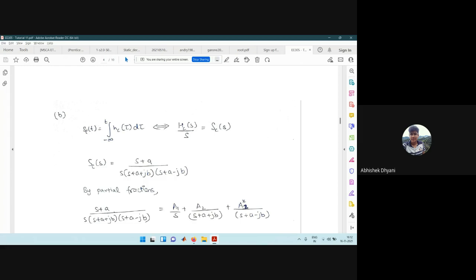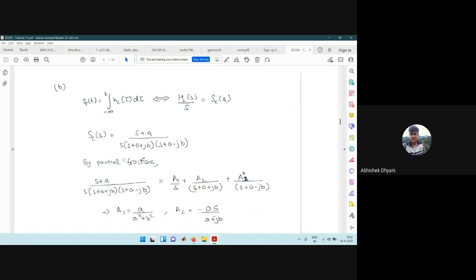So we just applied this Laplace, and we got this thing. Now we already know H2(s) from the previous part, and S2(s) will be that divided by s. So whatever term we had last time, we just divided by s, and then again we take the partial fractions, right? Because now we have to apply the impulse invariance in this step response. That is why we are doing this.